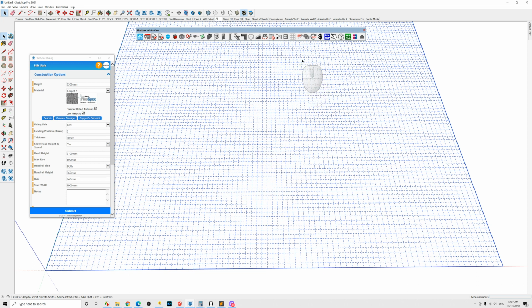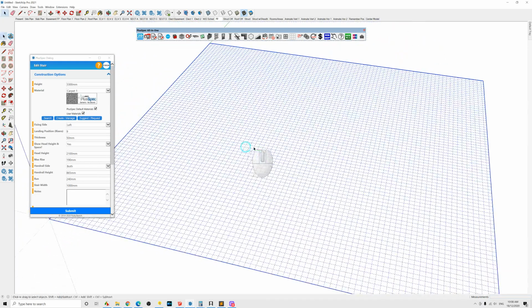Okay, so the next one is the Purge tool up here, and if I click that, what it's going to do is, when you've gone through and deleted something, SketchUp will hold them inside of a storage area, and that can slow you down a little bit. So the Purge tool, and the reason why I've got a little running man on it, is it speeds up SketchUp. So you can go through and purge components only, materials, which is basically the texture that's on the face of a wall, or styles that could be inside of your scenes, and clean them up automatically. Just click okay, and it will go through and clean up. You notice that when I deleted those things, I had 133 components, which basically made it go faster.